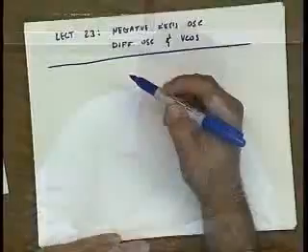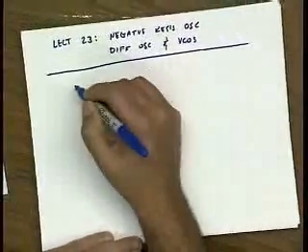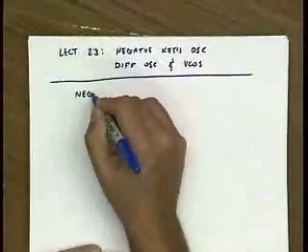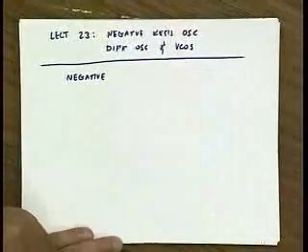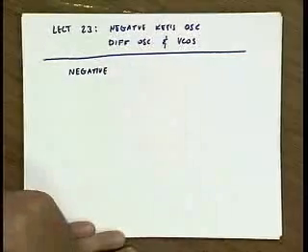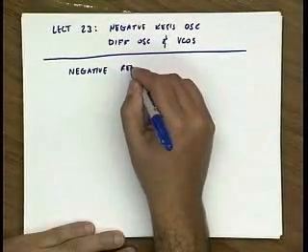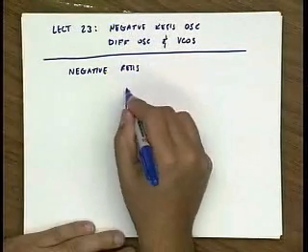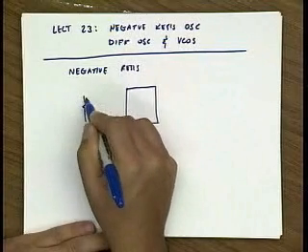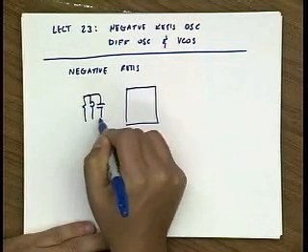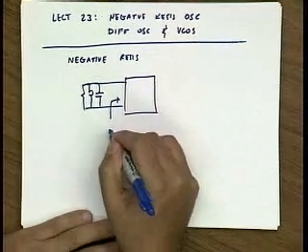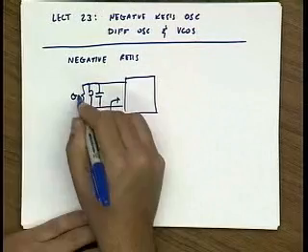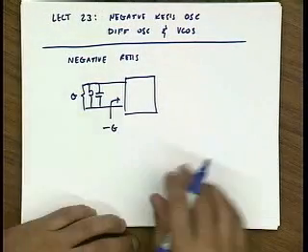Okay, so let's pick up where we left off. Let me step back a little bit and review what we've done so far. In the first lecture on oscillators, we looked at the feedback approach of analyzing oscillators, positive feedback, loop gain. Last lecture, we looked at the negative resistance perspective: if we have a lossy LC tank, our active device is in effect a negative conductance that exactly compensates for this loss.